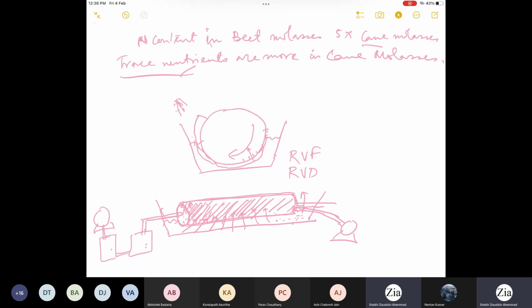So here this spray will have clear liquid, obtained from the inside of the vessel through this pump. Essentially this liquid spray will ensure dislodgement of all residual liquid from the system, and then you will have another wash cycle introduced by clear water, and then finally you will have a mechanical scraping device like a small blade.